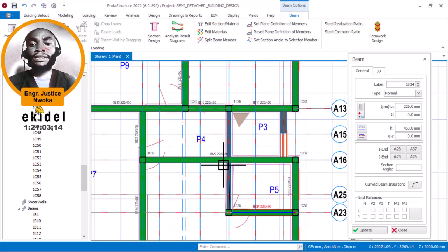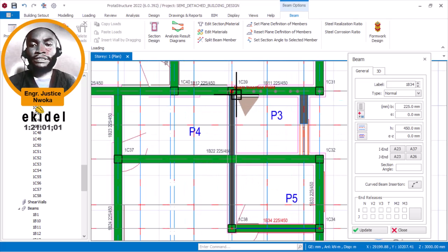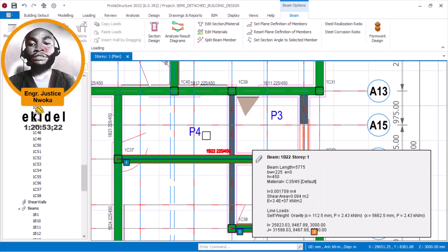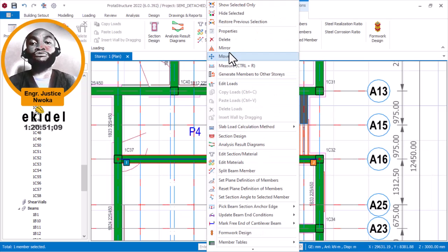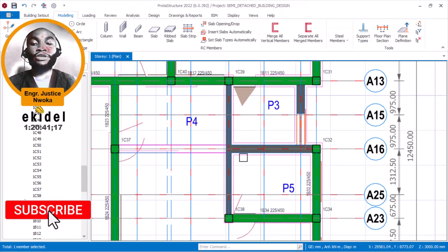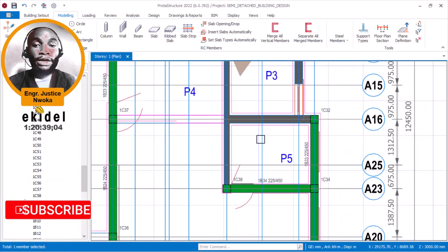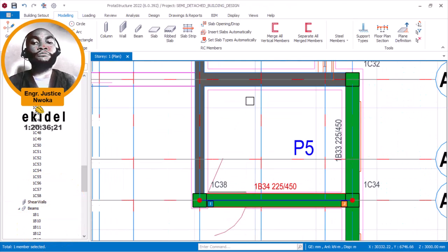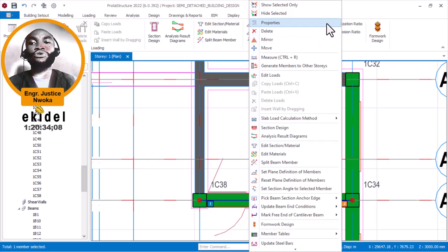That's so bad. Now this beam here, I'm going to remove it because this is meant to be the primary beam, okay? So with that now, I'll remove this, so let me just undo on it, just delete this. So you can see why it is best to do your structural framing, because it makes you understand the building plan. Okay, so I'll remove that right now and make this my primary beam. As you can see, this was meant to be the primary beam. So you must take all this into consideration while you are doing your structural framing. Okay, that's fine.